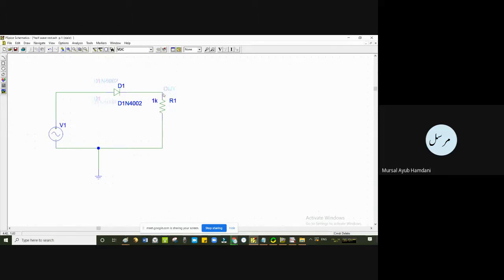However, if you want to note down some terminal, you simply do it like this. You click on this, make one arrangement like this, escape, and then double click on it, and it will ask you to set the attribute value as a label. So you name it as up. This is just a variable name, for the voltage across that particular resistance.